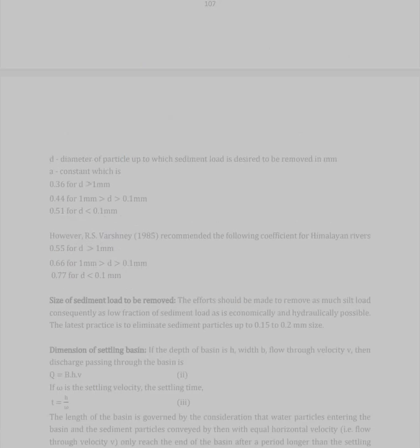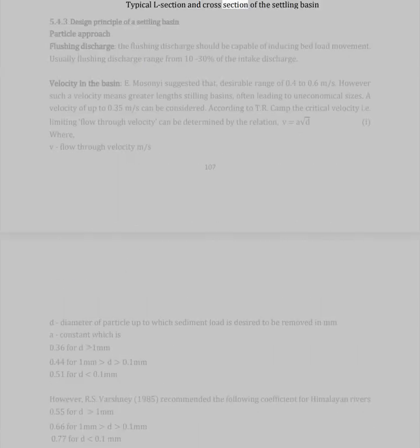Figure 107. Typical L-section and cross-section of the settling basin. 5.4.3 Design principle of a settling basin. Particle approach: flushing discharge. The flushing discharge should be capable of inducing bed load movement. Usually flushing discharge ranges from 10 to 30% of the intake discharge.